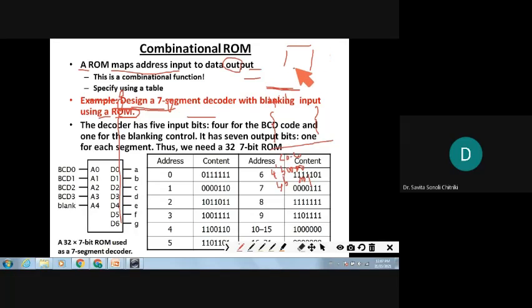I want to store 0, so I need to eliminate this one. What is there: A B C D E F and G. Only G has gone 0 whereas the rest have all gone high. Active high indication means this 7 segment display is common anode display, so high is being sent.